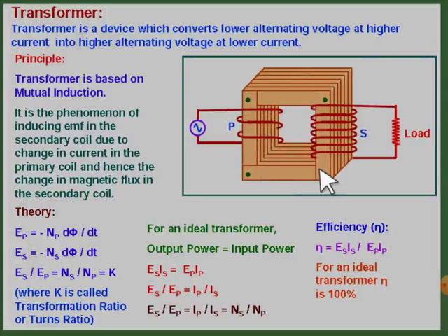In order to prevent the loss of electrical energy in the form of eddy current in this big or huge core, we make it laminated. Moreover, the laminated soft iron sheets are insulated from one another by an insulating material like varnish.